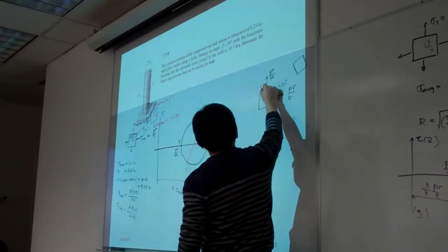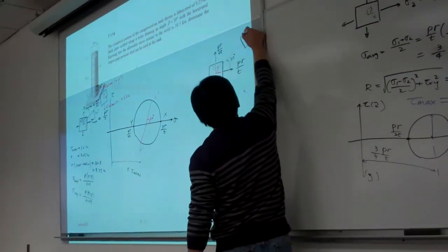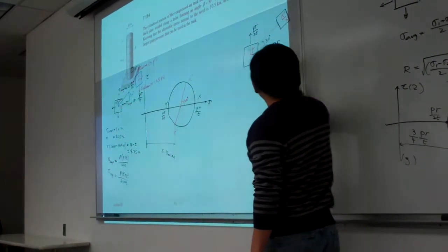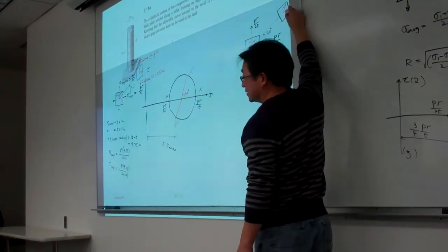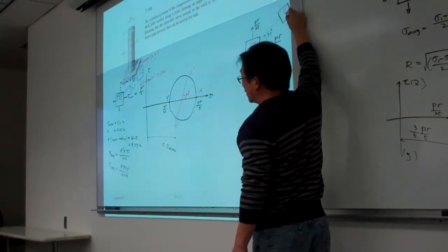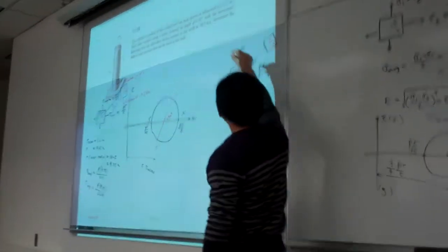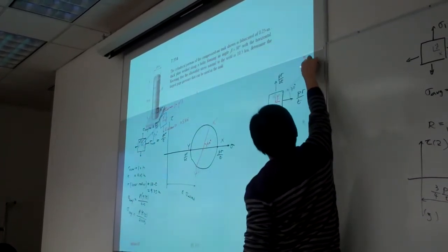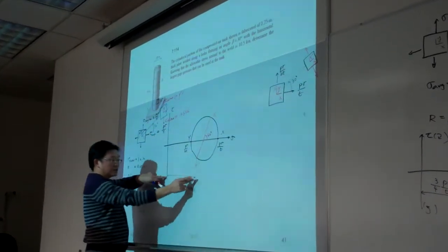So, okay, for example, my question is then why is the allowable normal stress associated with the y prime? Okay, wait a minute here. So here is the transformed x prime and y prime. And again, this is the orientation in the welding direction. In the problem statement you can see, the third line, it's the allowable stress normal to the welding. So that is the normal to the welding. So here we're looking for this normal component, which must be less than the allowable. So that means it is represented by this coordinate.